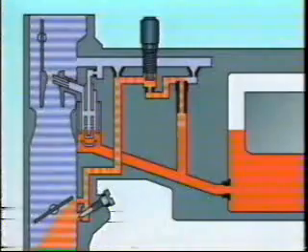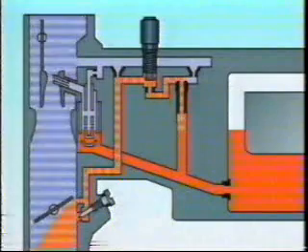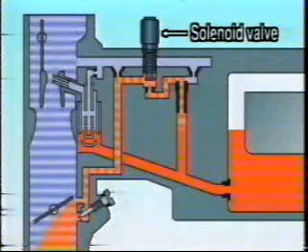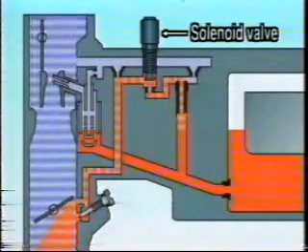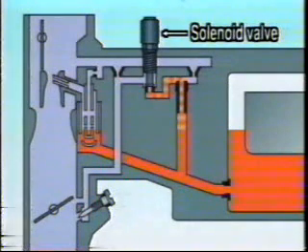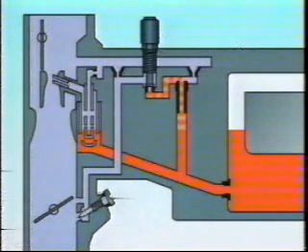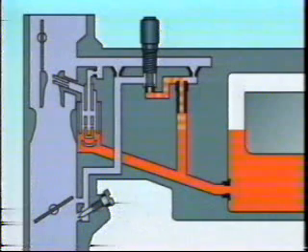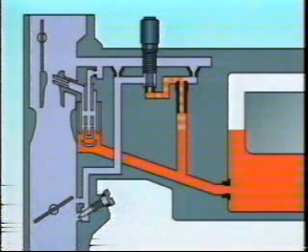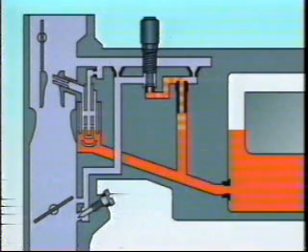In the primary low-speed circuit, there is a fuel cutoff solenoid. When the ignition switch is off, the route is closed and the fuel supply is interrupted. In some engines, a fuel cutoff solenoid also activates when the engine is running at slow speeds.